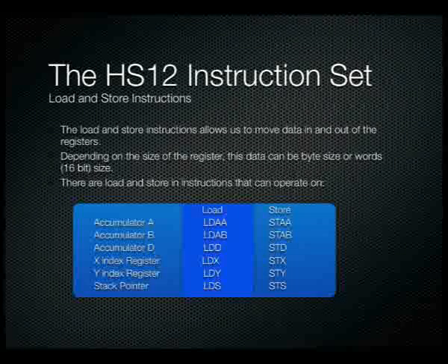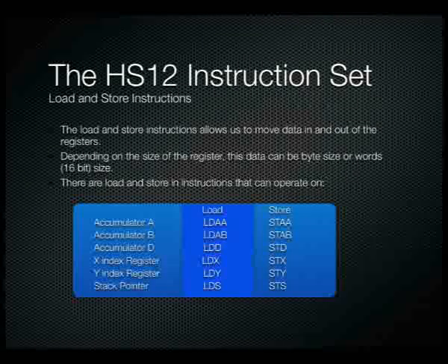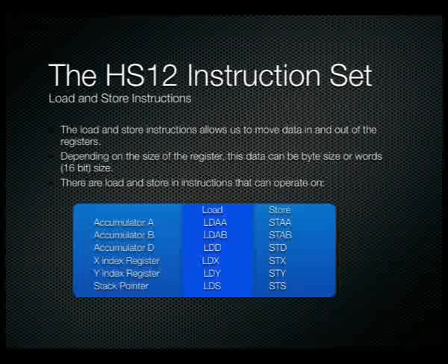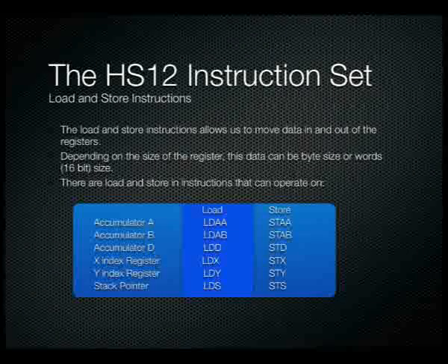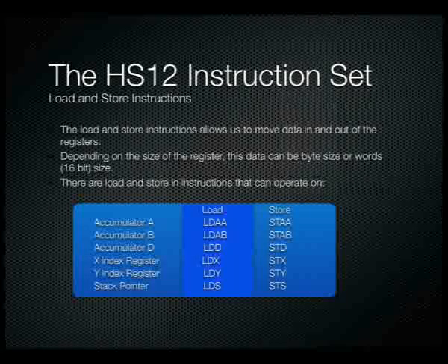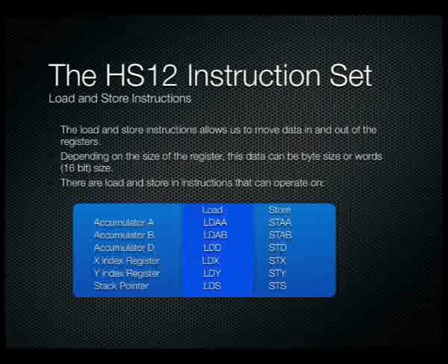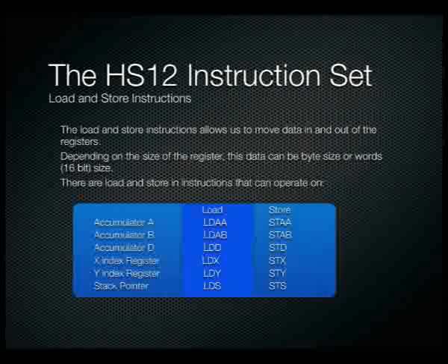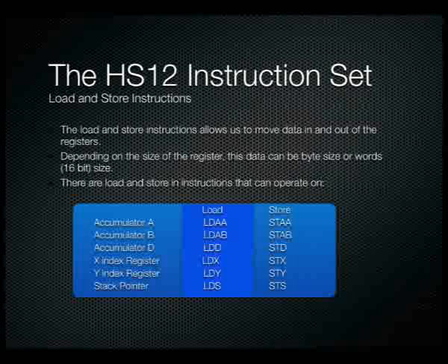There are basically load and store instructions that can operate on our accumulators A, B, and D, our index registers X and Y, and of course also on our stack pointer. They are the registers that we can use to load data in and store data out of with these instructions.